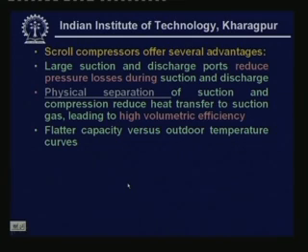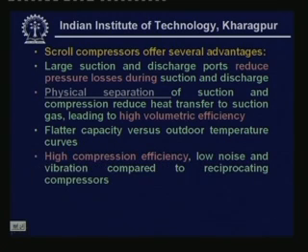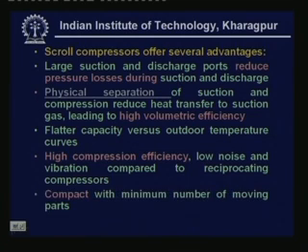In addition, of course, the re-expansion losses are also quite less in this one, and there are flatter capacity versus outdoor temperature curves. Another advantage is higher compression efficiency, and low noise and vibration compared to reciprocating compressors. They are compact with minimum number of moving parts.